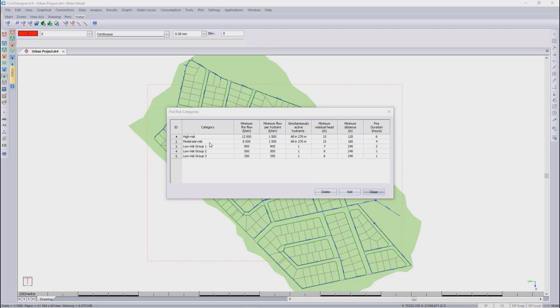We have then the moderate risk areas. These are areas of risk of fire and the spread of fire is moderate, such as industrial areas or areas zoned as general residential with a floor space ratio less than 1, and where buildings are not more than 3 stories in height. Commercial areas normally occur in residential districts where buildings are not more than 3 stories in height.